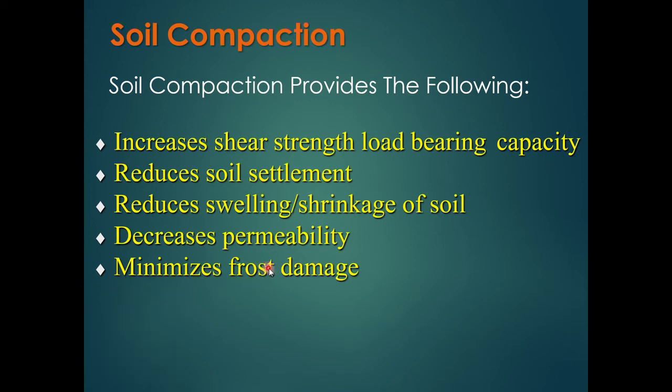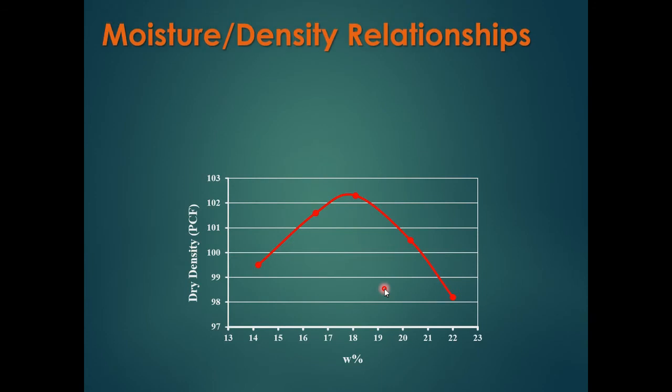I guess they go hand in hand. Frost damage, right? We compact it together, less water in there, less frost damage. Increases erosion resistance. Okay, so we need those particles touching, so there's friction, so when it rains it doesn't want to carry those particles around. Okay, key, erosion. All right.